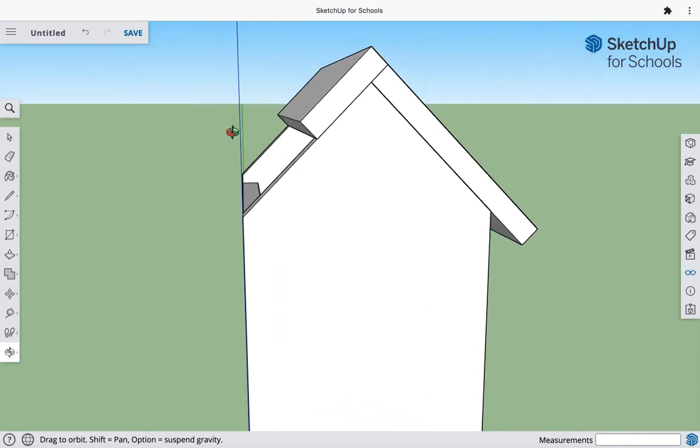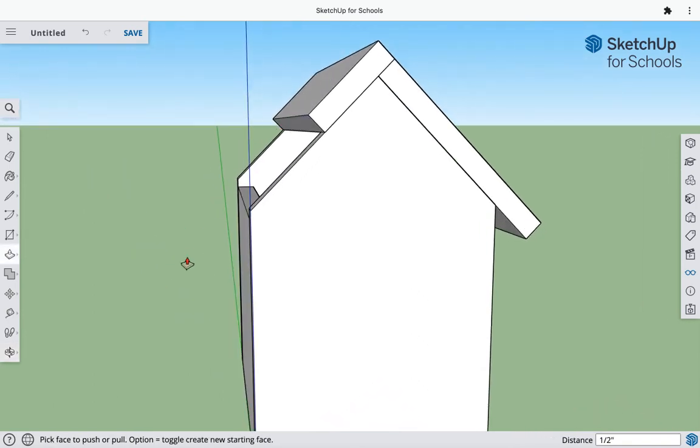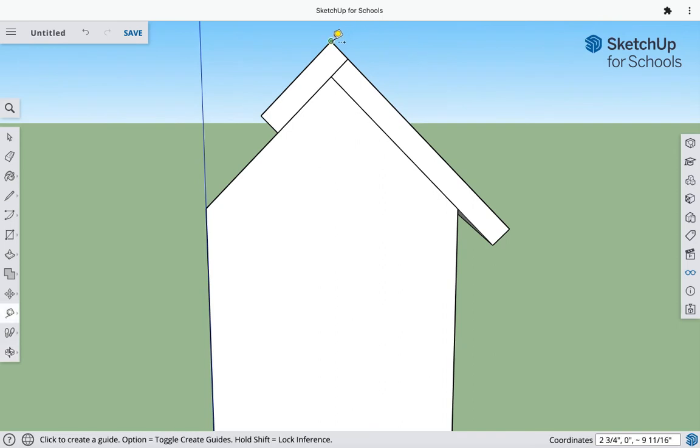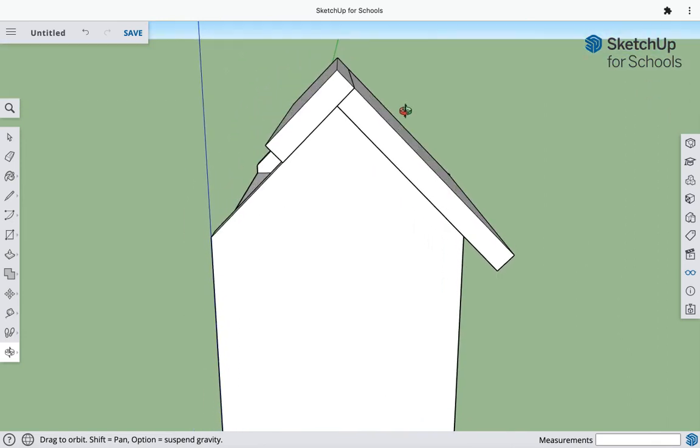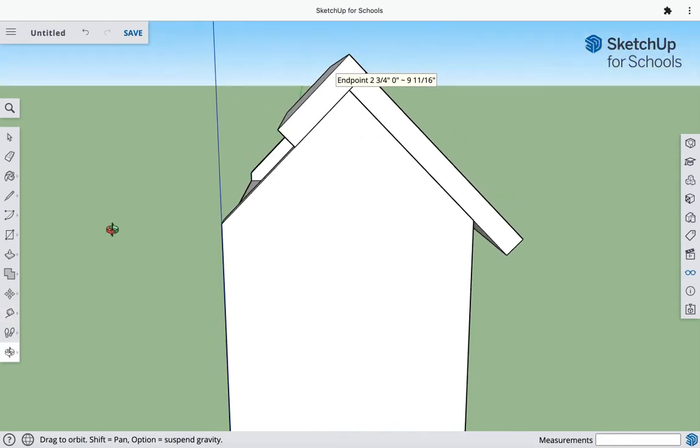Okay. So now before we do the other push-pull piece, we got to pull this piece down right here. Let's go ahead and pull up the tape measure tool again. And by the way, I'm orbiting around so easily, a lot of times you'll have to press O to orbit. But if you have a mouse with a scroll wheel, you can click in on that scroll wheel, hold it, and it'll take you into orbit mode. That's the way I've been orbiting around. If you don't have that, then you'll have to press O on your keyboard and then orbit, or come down here to your orbit tool.